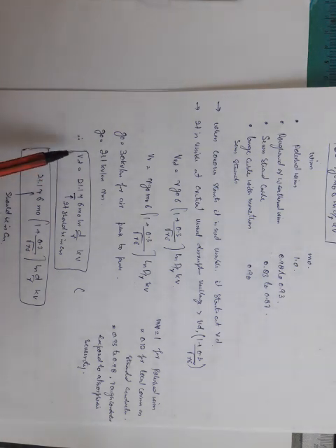Since you will see here, delta is unitless, M0 is unitless, and ln of D by R is unitless. So the multiplication should give us the value in kilovolt. Since G0 is in kilovolt per centimeter, that means R should be in centimeters.